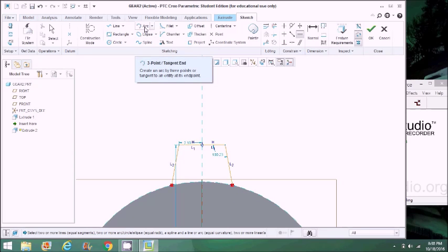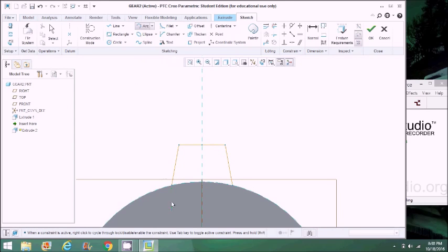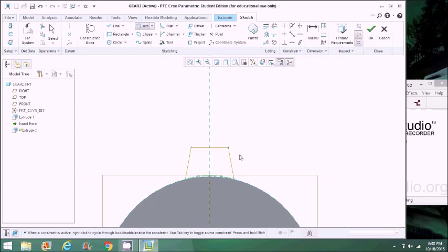So of course we want to enclose that, so we'll use the arc tool. So just click once on the arc and then click once on each endpoint and then once in the middle, and you will get an arc. And then again, to get out of the arc tool, you will click the roller button on your mouse. And as you can see, it's now shaded, so if that's how we wanted it to look, we could extrude it and everything would be fine.